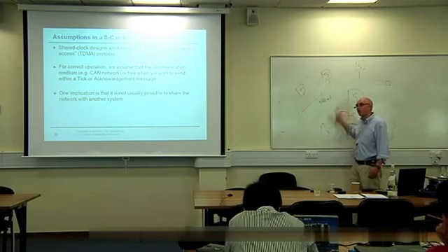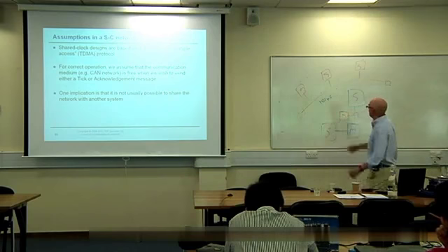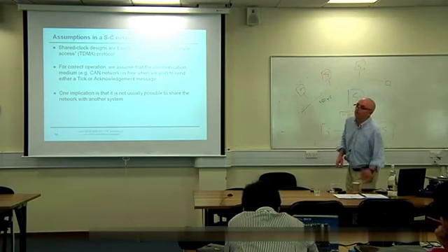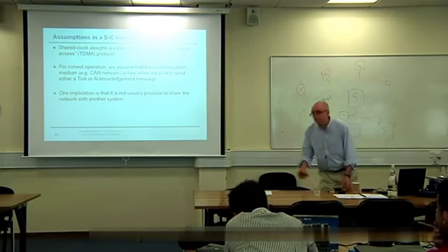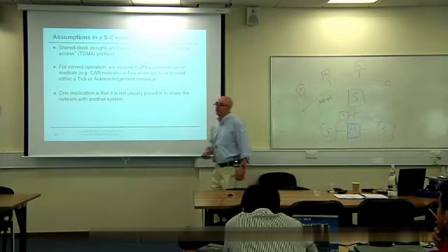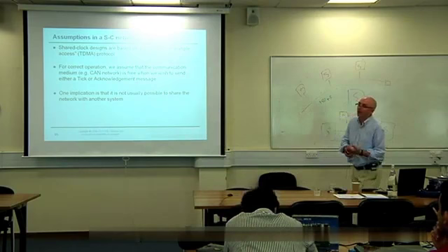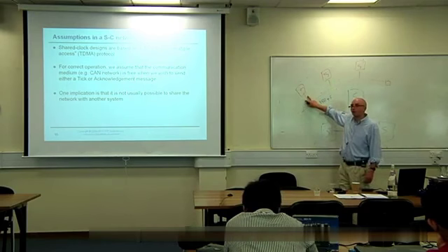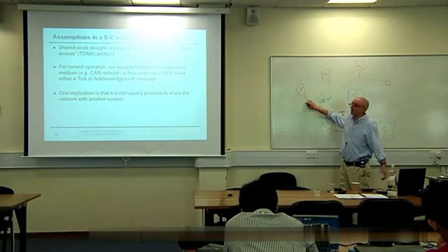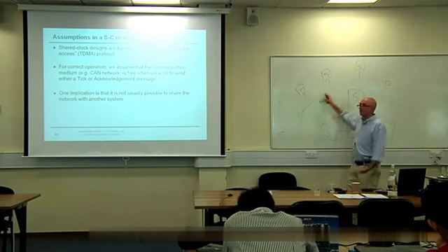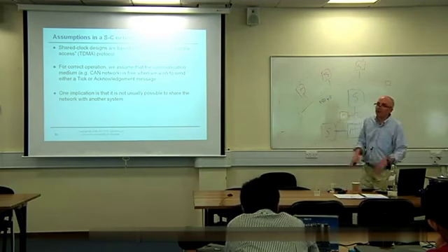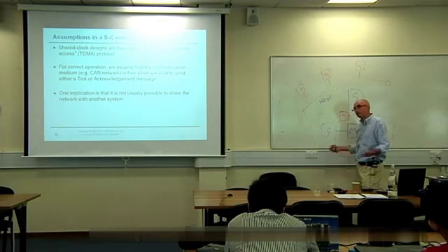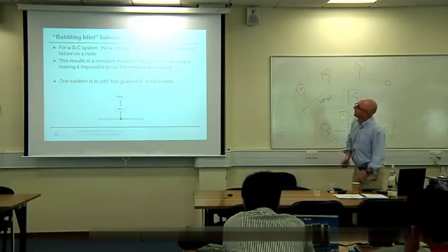So we can't afford to wait 150 microseconds to get a message through, and it might be 3 or 4 times 150 microseconds if there are 3 or 4 higher priority messages stacked up trying to get through. So we need control over the bus for these parts of the system, and that's sometimes challenging to do. Sometimes organizations who are producing these systems are only responsible for one node, and that presents significant challenges because not everybody contributing to that system necessarily draws up the system schedule. Sometimes that's a bit blurred.